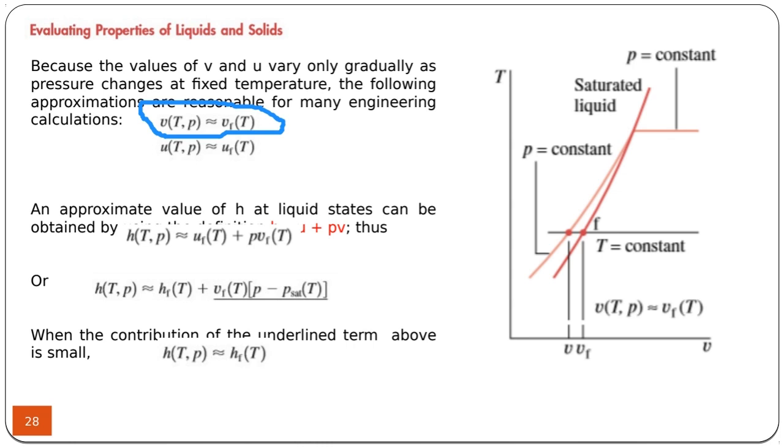And similarly, you can do the same thing for internal energy. For enthalpy, we need to use something additional. The enthalpy in this liquid zone is equal to the enthalpy of the saturated liquid at the given temperature plus this term.